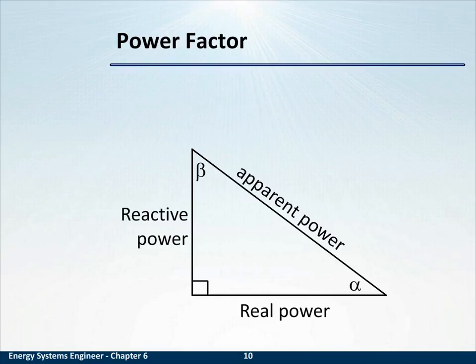Typically, a motor likes to be loaded between 50 to 100%, with 75% being a typical place to determine the highest efficiency of a motor. Well, what this graph shows you is that power factor is similar. Similar meaning that if you underload, your power factor will be too low. With both power factor and efficiency coming up to 1 as their maximum, what this graph shows is underloading and power factor is a similar consequence to underloading and motor efficiency.